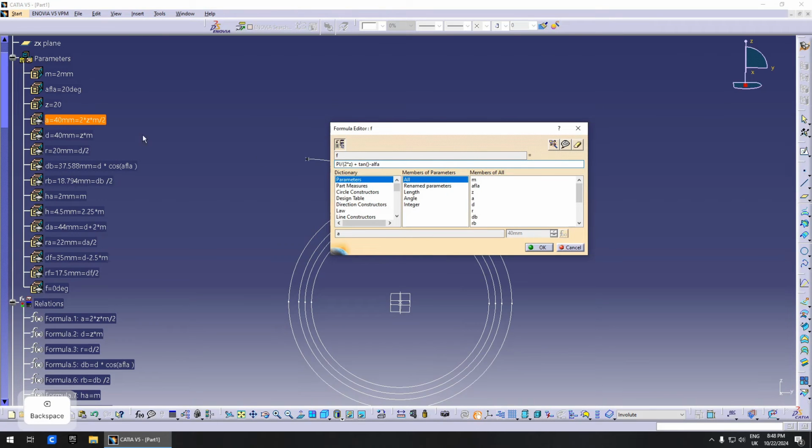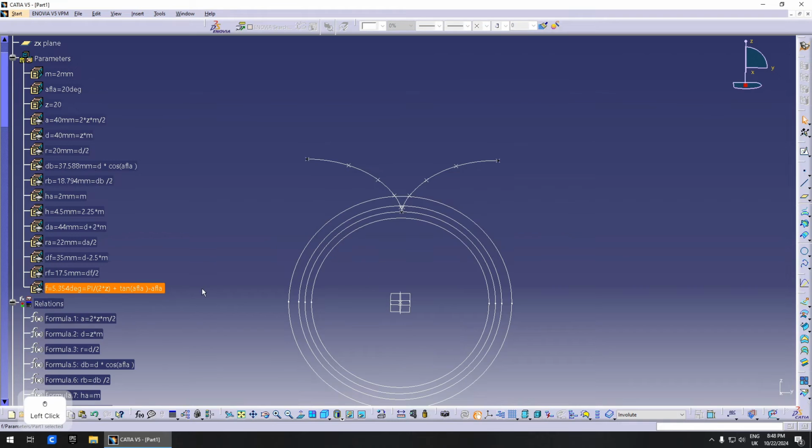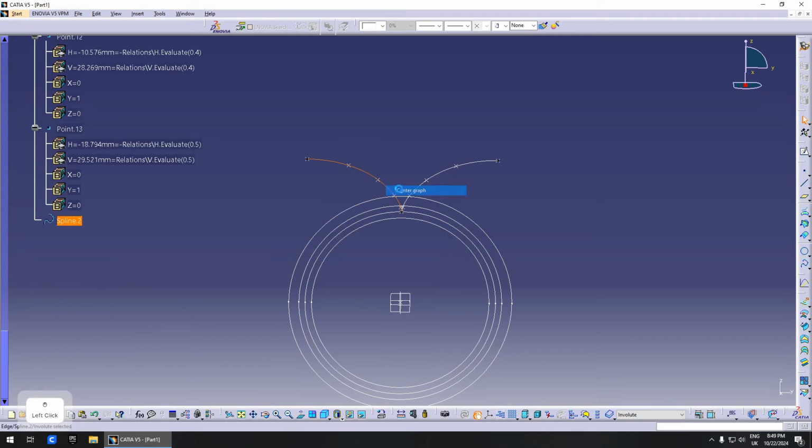Normally, when you have errors in writing formulas, it's because it doesn't recognize the parameter. So what I had to do is delete the alpha here and double click this to get the connection to this parameter. Right, and this one we will have to then rotate.